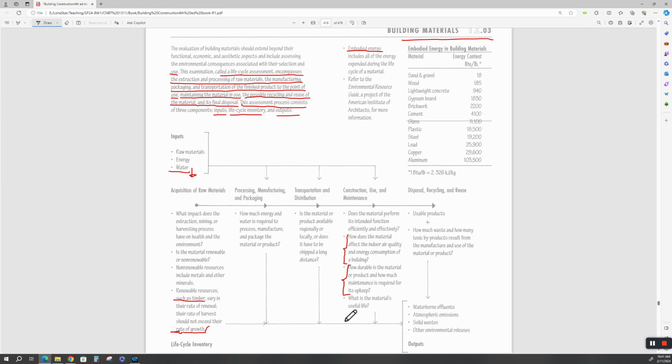Okay. Now your manufacturers are all going to stretch these claims for useful life. A lot of people got sold cheap vinyl siding to go over their house. Don't ever have to paint it again. Yeah, in about 15 years down here, in this heat and sun, that vinyl siding started getting brittle and start cracking because it's outgassing.